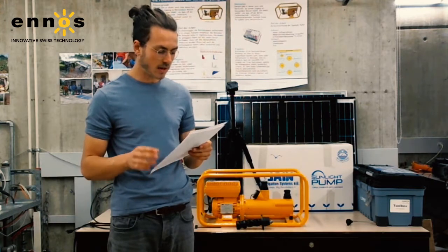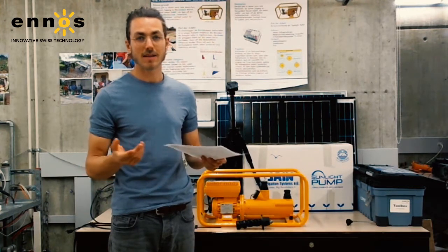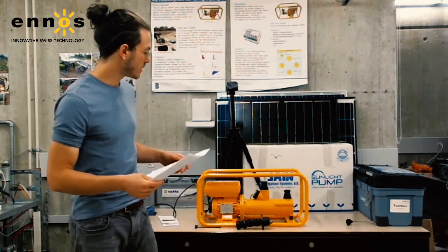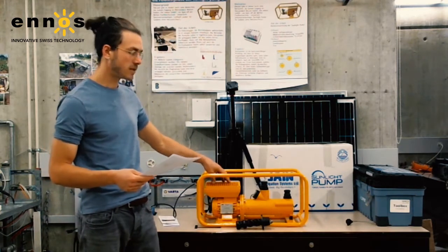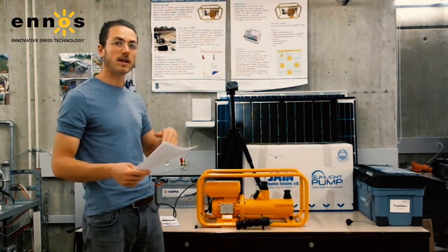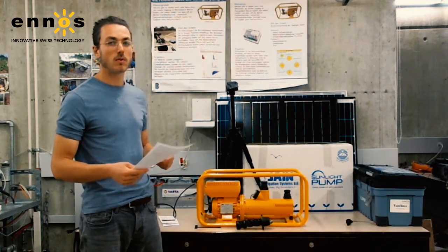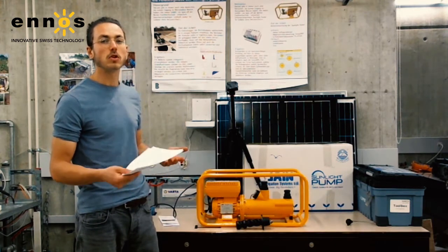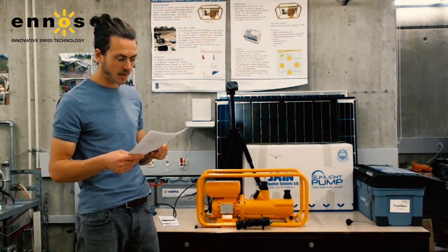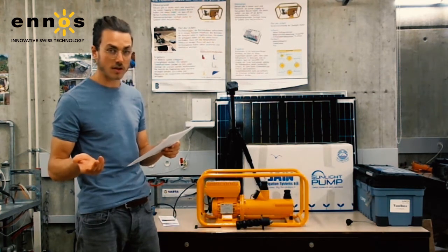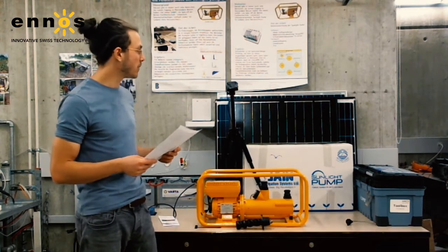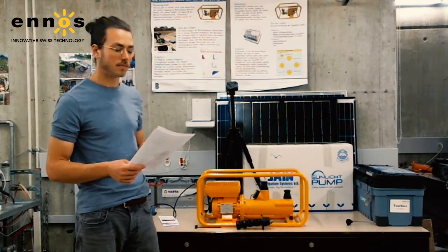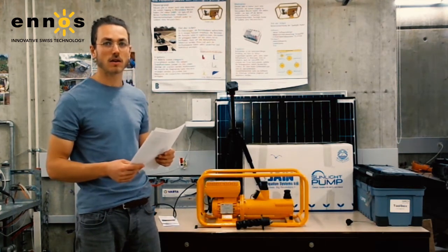Next off, we've got our maximum input current. This is at 9.5 amps, and this is the maximum amperage that our sunlight pump can take. Here, if we exceed the amperage, we will not damage the pump, but the pump has a cutoff point of these 9.5 amps and will simply not be able to take up any more input current. So if our solar panels have more than these 9.5 amps, the cutoff point is there. Again, this information can be found on the back of the solar panel.